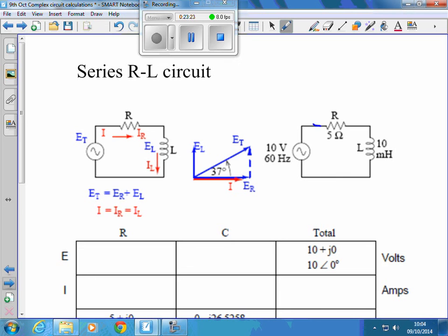In a series circuit, there is only one current because they're in series. So generally, you would make the current what's called the reference phasor, or the one with 0 angle in a series circuit. And then you would say what are the angle of the voltages from that 0 current. So you'd say the voltage is leading or lagging the current in that circuit. So we got our current phasor in red there, and then the 3 voltages. So we got the voltage associated with the resistor.